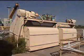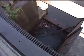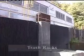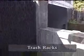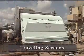There are usually two types of screens used to filter out trash in a once-through system: coarse screens and fine screens. The coarse screens, or trash racks, sometimes called trash rakes, are large mesh screens that filter out large debris, such as logs or branches. The fine screens have a smaller mesh to filter out smaller debris. Typically, traveling screens are used for this purpose. They can be rotated in and out of the water as needed so that the debris can be cleaned off. The motor-driven traveling screens cycle based on the differential pressure across them.